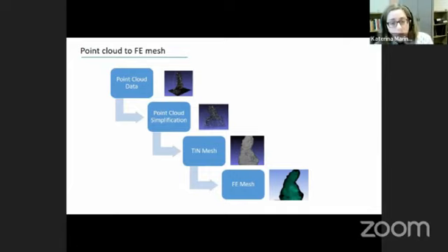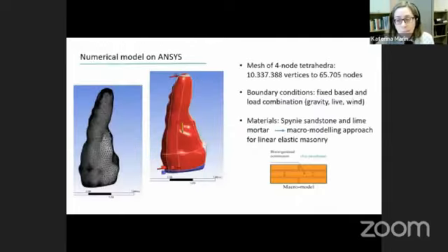The thin mesh was used as the basis for the creation of a three-dimensional solid structure in SolidWorks that constituted input compatible with finite element commercial software, such as Abaqus or ANSYS. ANSYS Workbench was used in this case, with the resultant model balancing computational cost and accuracy with respect to the needs of this project.